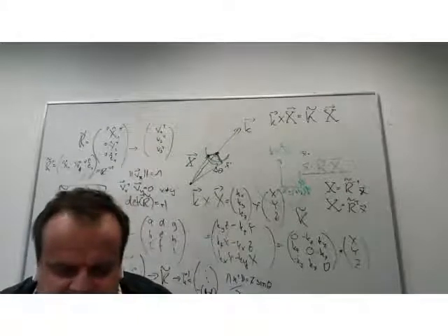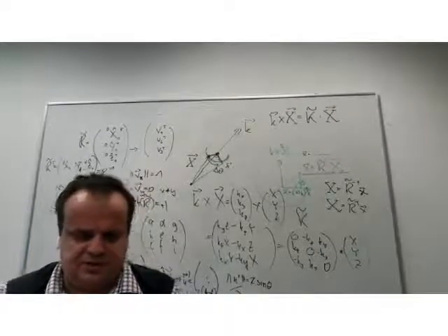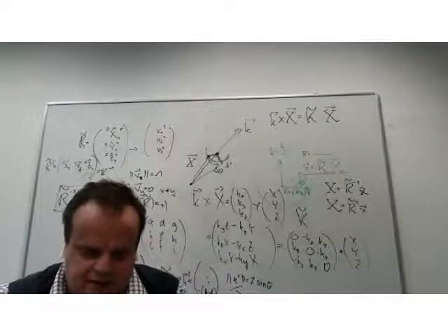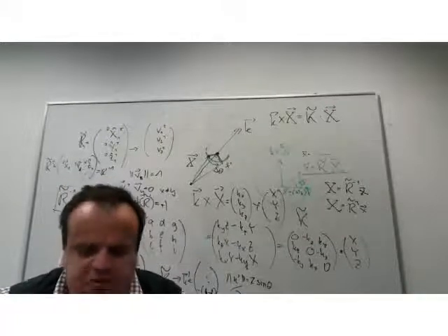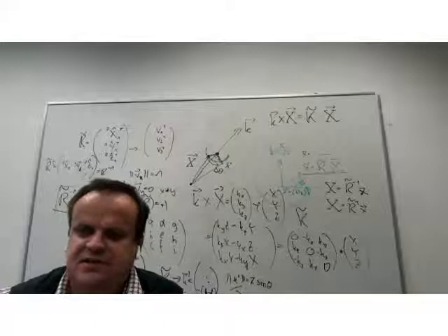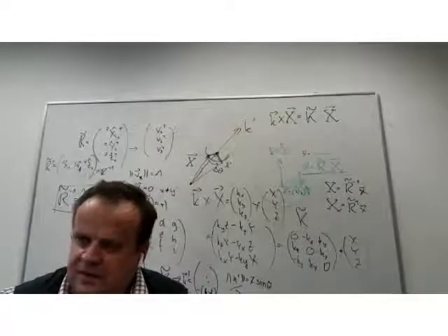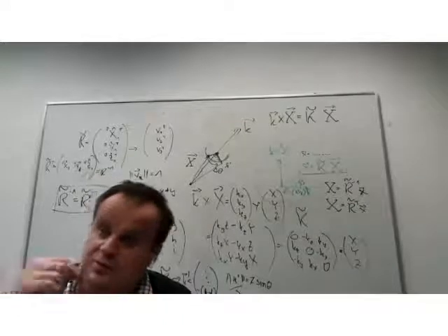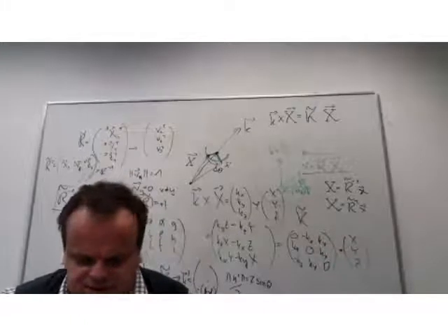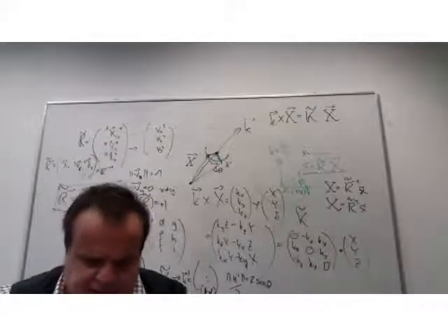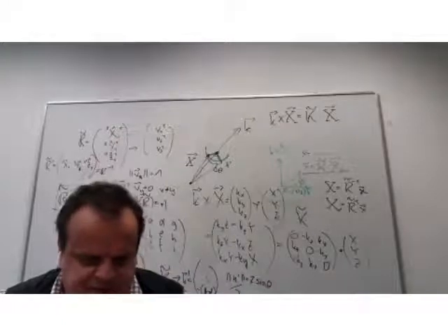Why is it important? It's important because this is the natural way the rotation happens in space. And this representation has no singularities. And this axis-angle representation is exactly what we will be using later in our Jacobian representation of the robot. So just remember this. Remember that from the rotation matrix, you can always recover these elements just the way I explained.